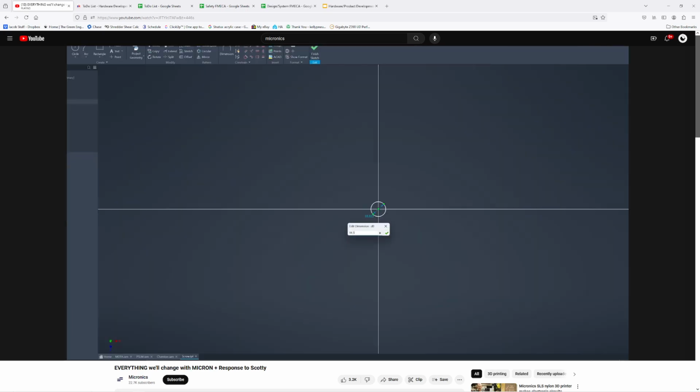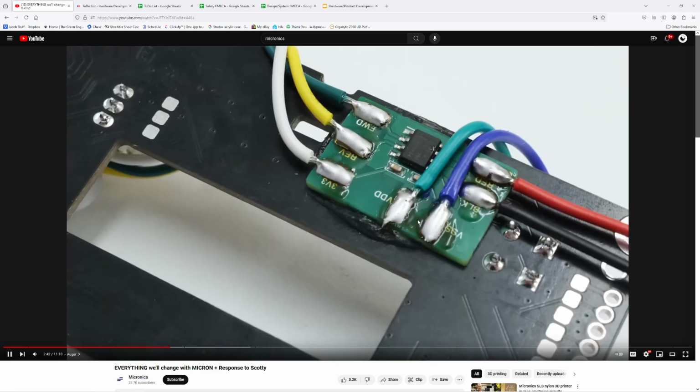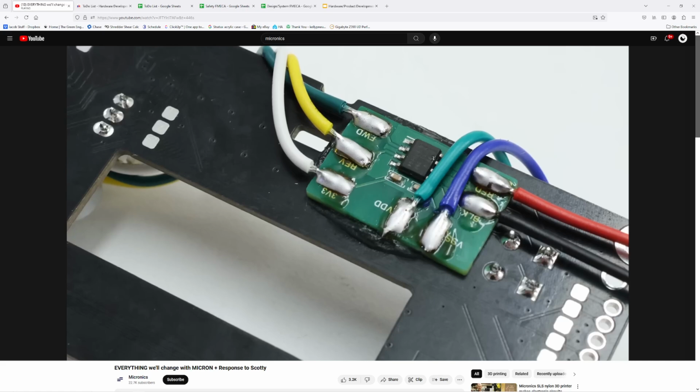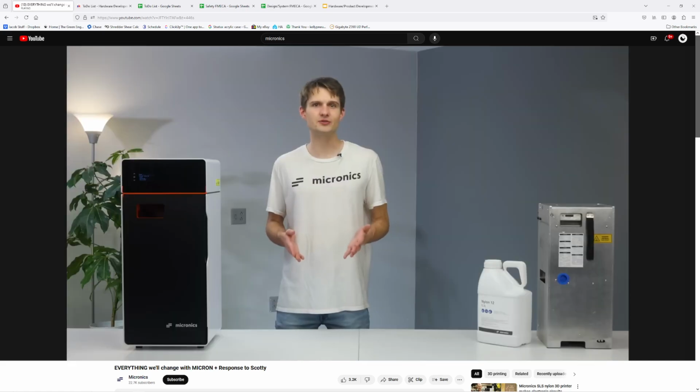One of the 5 machines experienced an auger jam. To fix this, we simply need to increase the clearance. Again, 1 of 5 is not good. 2% or less. Additionally, we've modified the control board to allow the motor to reverse for minor jams. While tapping the auger with a hammer might...